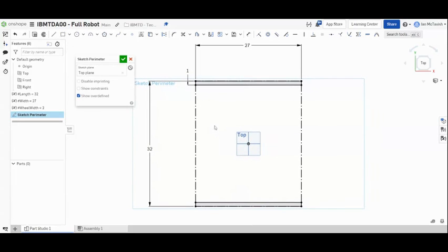I'm going to do my side pieces. So what I'm going to do is I'm going to have a square tube along the front, a square tube along the back, and a square tube on the left and a square tube on the right. Now, how I'm doing this is going to be a West Coast drive. So my rectangle is going to be inside here, and later on you're going to see why. So I'm going to click the rectangle tool. So remember, that's G. I'm going to hold my mouse over this. I'm going to click once. I'm going to move down. I'm going to make sure it's on that line, and I'm going to click a second time.